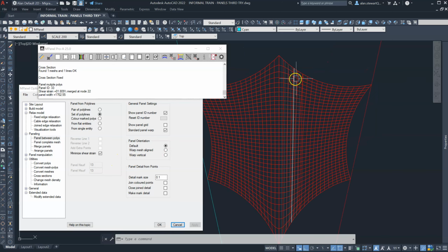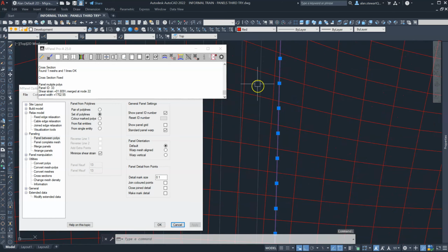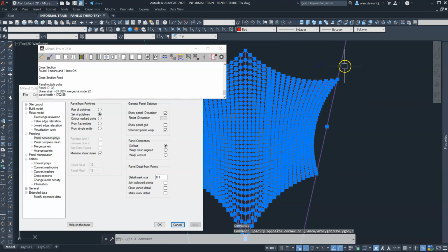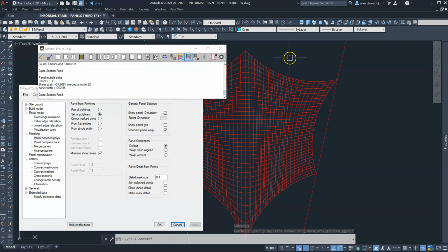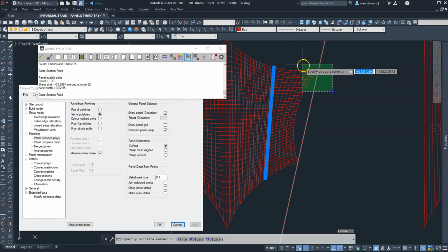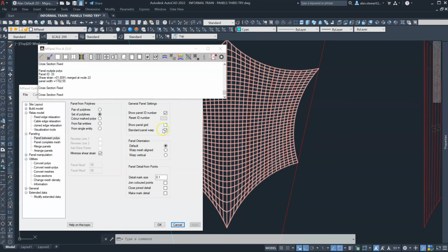So using this procedure, we would continue, select the last of the cross sections that were created, again the mesh and the cut line, and run the tool again. There's the next batch. And then finally, this last panel, we don't specify the fabric width.